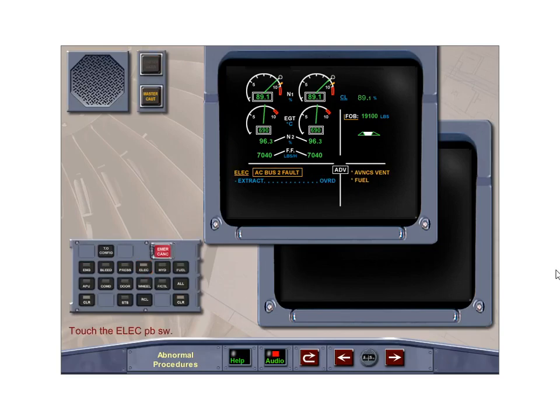The AC bus fault is the result of an AC bus losing power due to a fault on the bus. With an AC bus 2 fault, the lower ECAM display is lost as it has no power supply. The only ECAM action is to select the extract fan push-button switch to override, putting the avionics ventilation system in the closed-circuit configuration, adding air-conditioned air to the ventilation system. The status page will display a long list of in-op systems. Refer to FCOM 3.02.24, Abnormal and Emergency Procedures.